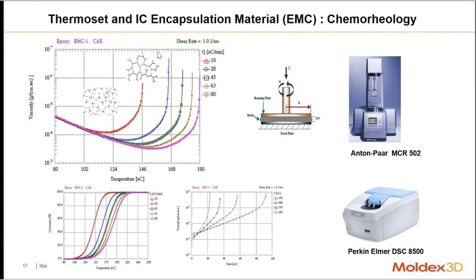So when we mold this kind of material, we need to check this data, and we want the feeding stage to happen in this area because the viscosity is low. Once the viscosity increases, there will be molding defects such as short shot. So we need to very precisely control the feeding patterns at the low temperature area. Of course, this is also related to the curing kinetics.